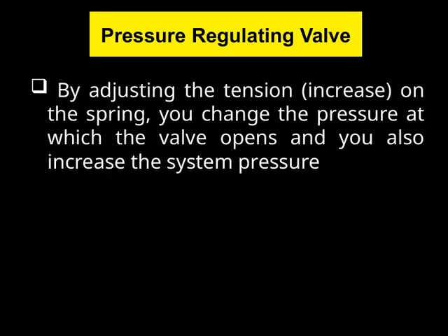Now, let's talk about how adjusting the tension on the spring affects the pressure at which the valve opens. When we increase the spring tension, it requires a higher pressure to overcome that tension and open the valve. Essentially, you're setting a higher pressure threshold for the valve to activate.